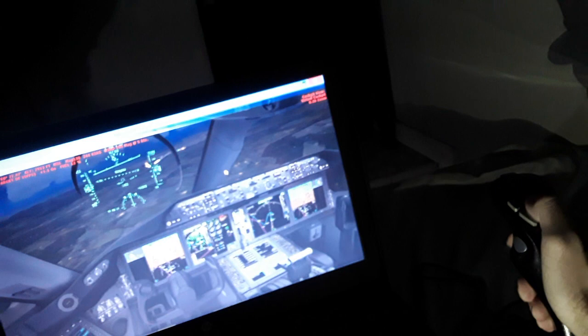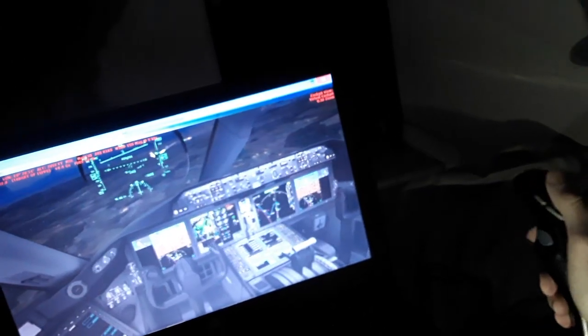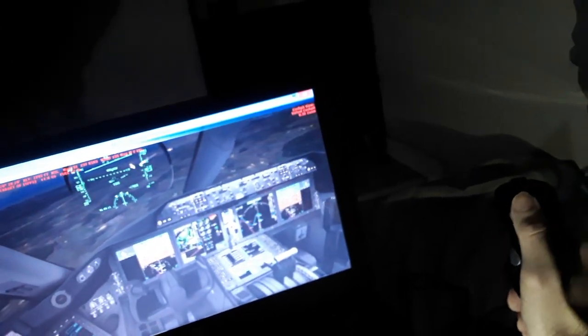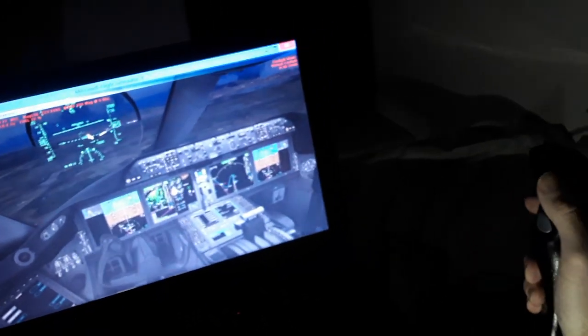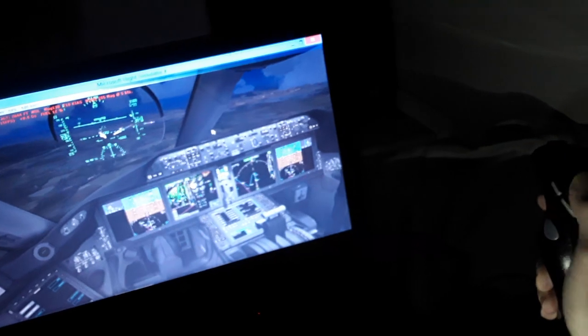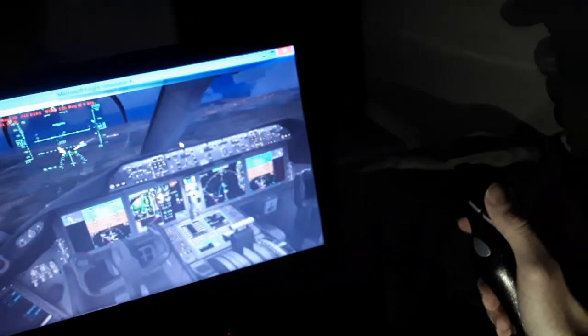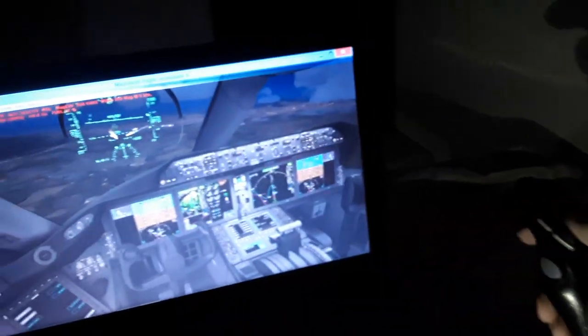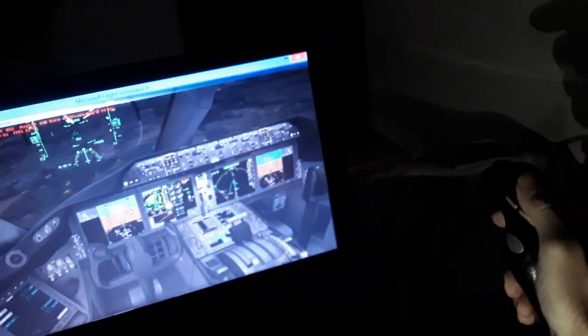So we have a little bit of side wind. We use right rudder, also flight controls to the right. A little bit more thrust will give us better flight control maneuvers when we have side wind, and a wind gust is pushing us to the side. Also use more flaps over here, so we need to increase the airspeed.